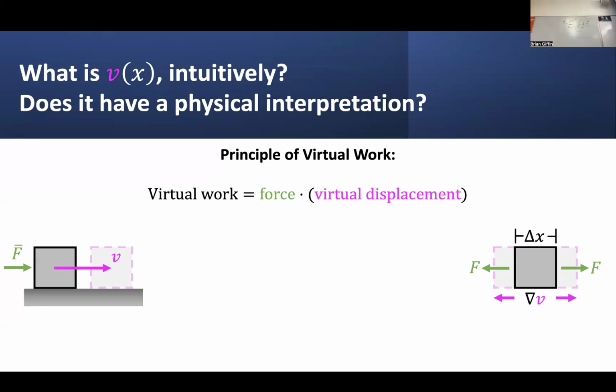Or in other words, if I had this virtual displacement field and I took its derivative, I could interpret that as an imaginary stretching that might happen internal to this material. And given the definition of this virtual strain field, I could come up with a definition of virtual internal work that would be done stretching this block of material, including whatever internal forces might already be acting on this block of material.